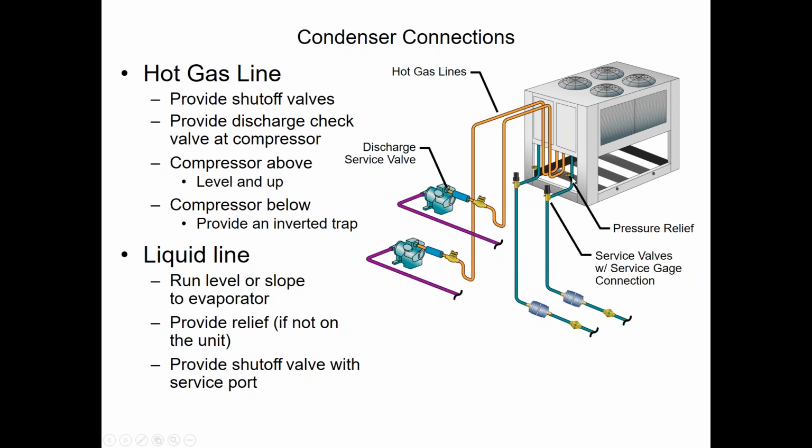Now, depending on what the total charge is, sometimes we have to pipe the liquid lines to some type of manual dump valve, a fireman's dump valve they can get to. Basically, in the liquid line, and I would always put it at the outdoor section, because that's ultimately where we want to get the gas. And the liquid line is going to relieve all the pressure the quickest. So hopefully that answers the question.